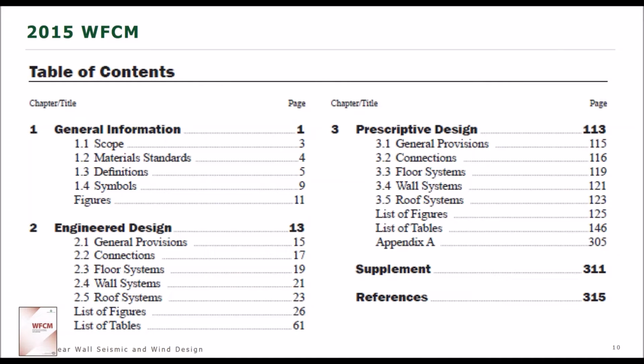But if you look at the way that the chapters are laid out, they are laid out in an identical fashion. So, you are allowed to, for example, if you design your floors using the prescriptive approach, that does not prohibit you from designing your walls with an engineered approach. You can't mix provisions within a system, but you can use engineered or prescriptive provisions for different systems within the structure.